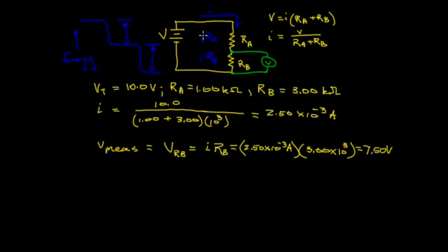The energy at the top of the pair of resistors is 10 volts. Some is lost in pushing the current through the first resistor, and our meter is set to measure the energy used in driving current through the bottom resistor. We can calculate the voltage by multiplying the current in amps times the resistance RB. The current is the ratio of the total voltage dropped across the pair of resistors divided by the sum of the resistances.